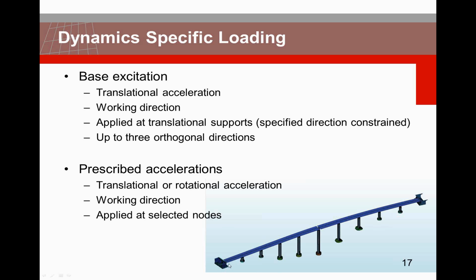And then when attached to time curves, as you can see later, you can make sure that, say, for instance, on this left side, the earthquake will slightly start earlier than on the right side. In this way, for large constructions, you can take this effect into account. While base excitation would say this entire bridge is going to shake all with the same motion at the same time, with the prescribed accelerations and dedicated time load curves, you can make sure that there is a time delay in when the earthquake arrives at each pier. It's also depending on your model what is most applicable.